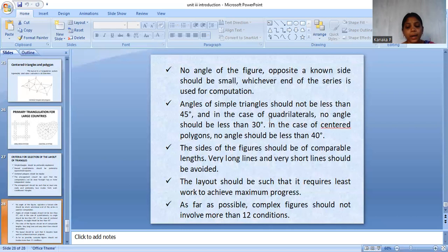The next one is the probable error of the mean. The arithmetic average is given by Em = √(Σv²/((n−1)n)), so Em = Es/√n. The next one is the probable error of a sum. The probable error of measurement is √(E1² + E2² + E3² + ... + En²), where E1, E2, E3, ..., En are probable errors. This is the error classification.